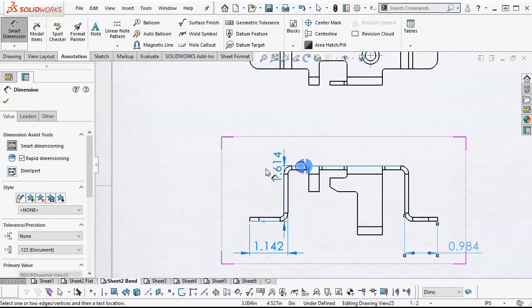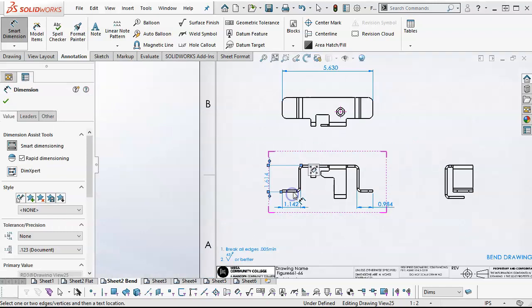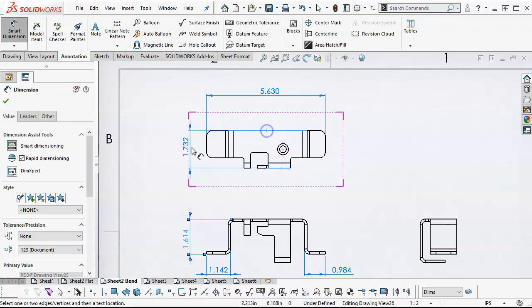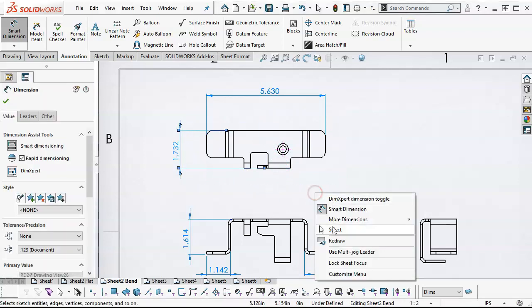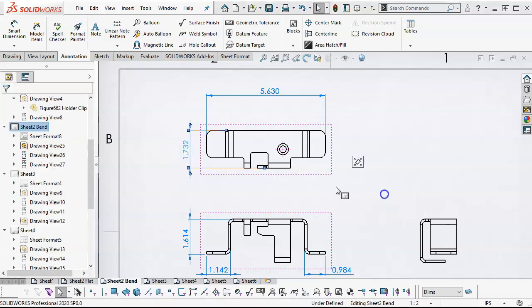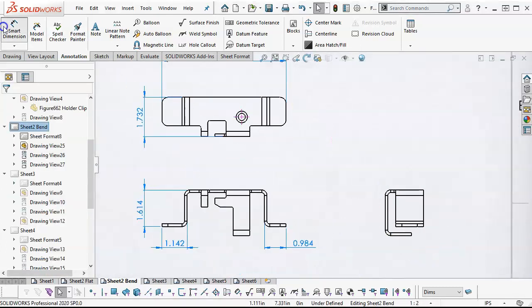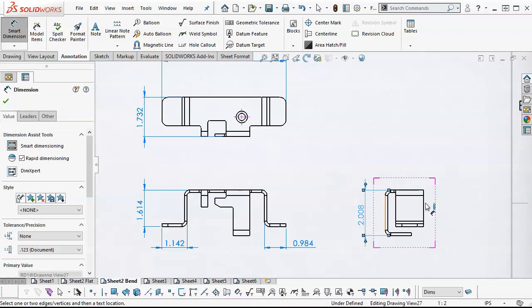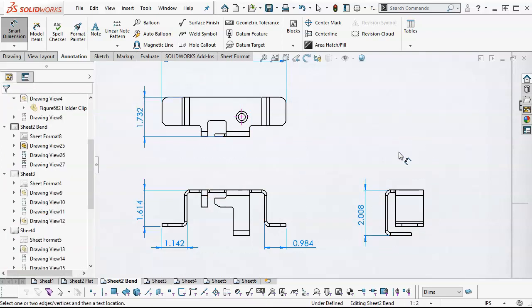So as long as I can give details of overall heights, lengths, widths, etc., I should have enough information here to do an after bend inspection to verify that we've ended up with the desired part. Alright, so from there to there, that takes care of the width. And that will give me an overall on the length. And also kind of ties in with the second tab, so I don't have to worry about that one.